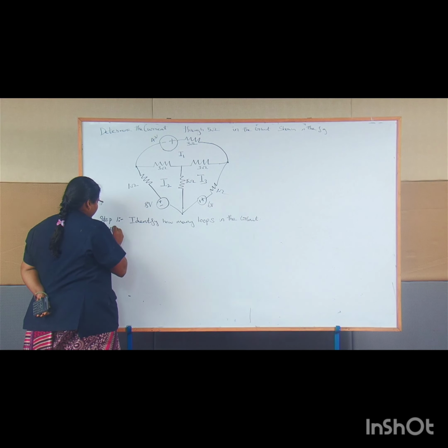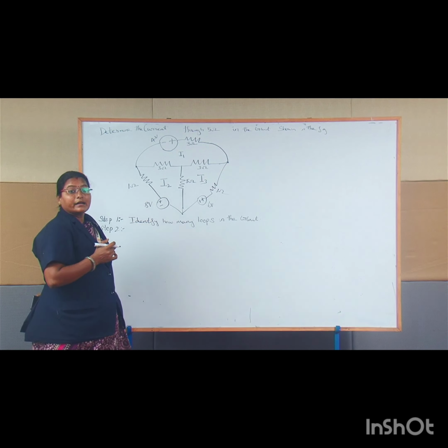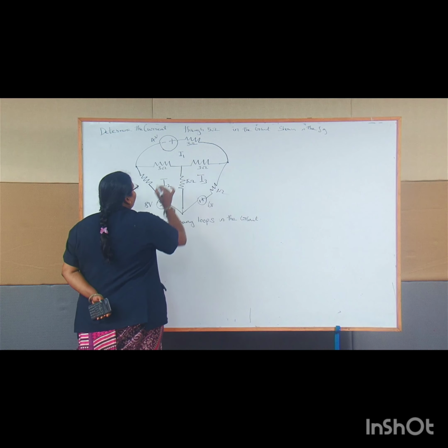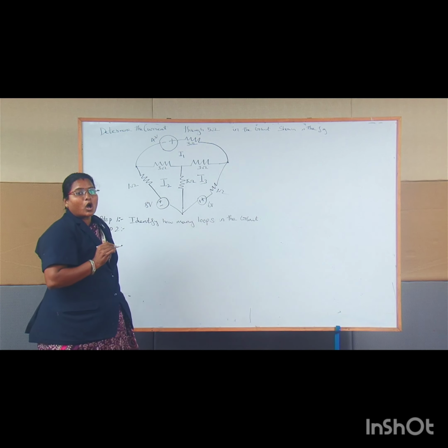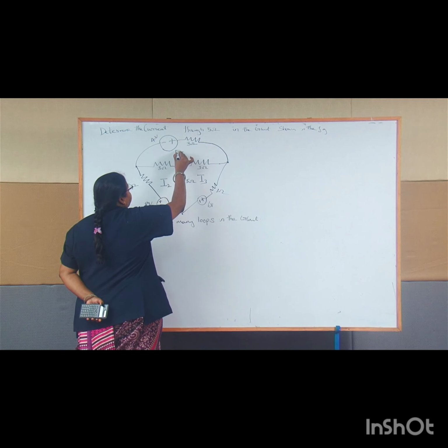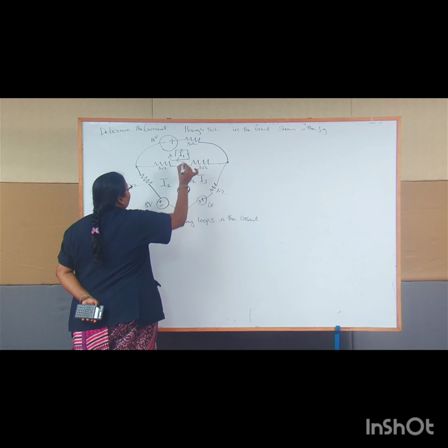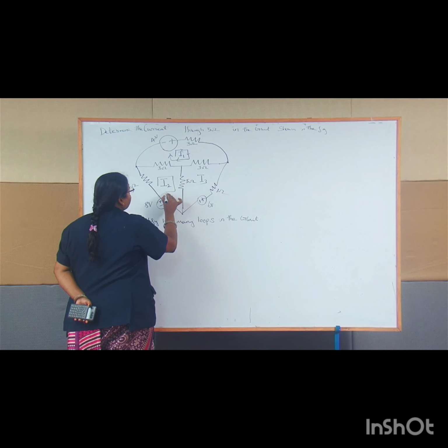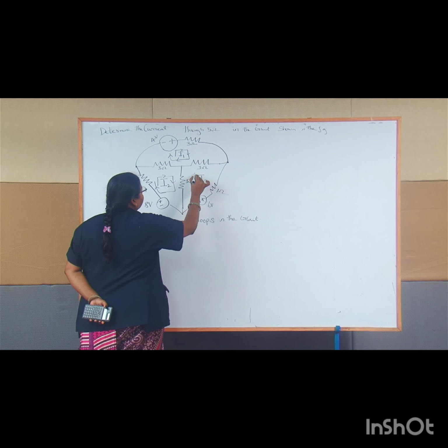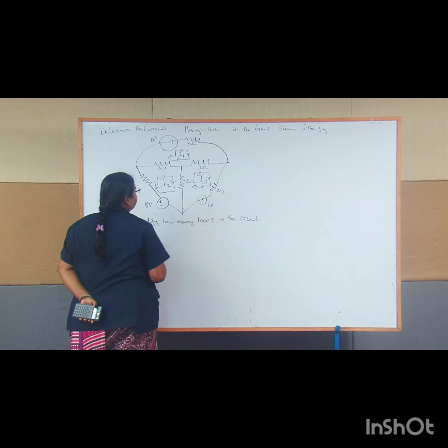Step 2, you have to assign the current direction. I am going to assign clockwise direction only. So I assign clockwise direction: this is I1, this is I2, this is I3.